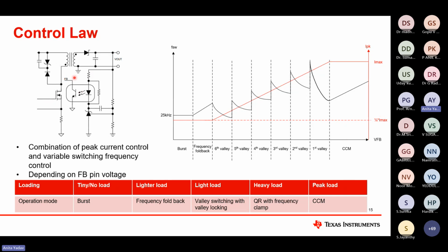So here is the COMP pin. We are sensing here, stepping it down, and then we have our compensation circuit, and an optocoupler is used here. This transfers the energy from the output secondary side to the primary side. Then this COMP pin is basically a kind of error amplifier output voltage, which goes to the controller and provides information if Vout is increasing or decreasing. Based upon that, it gets the information about the output power level, and thus changes its operating point.